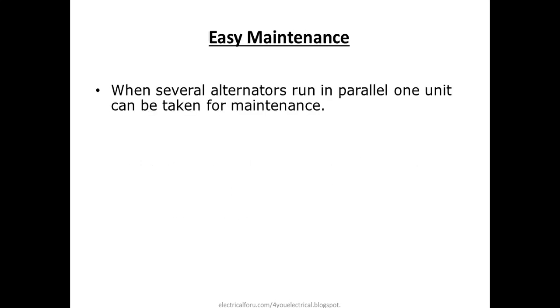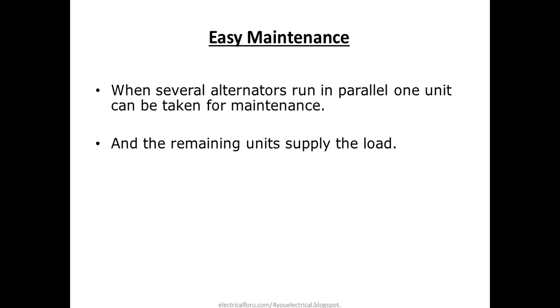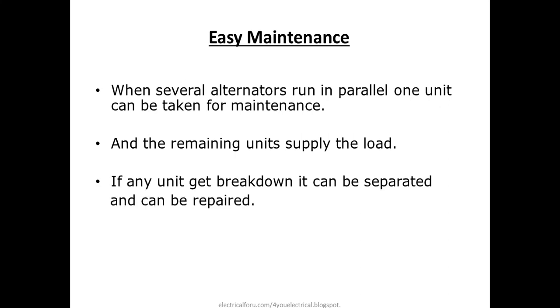Another advantage is easy maintenance. When several alternators are in parallel, one unit can be taken for maintenance while the other units keep running without interrupting the power supply, and the remaining units supply the load. If one unit breaks down, it can be separated easily for repair.